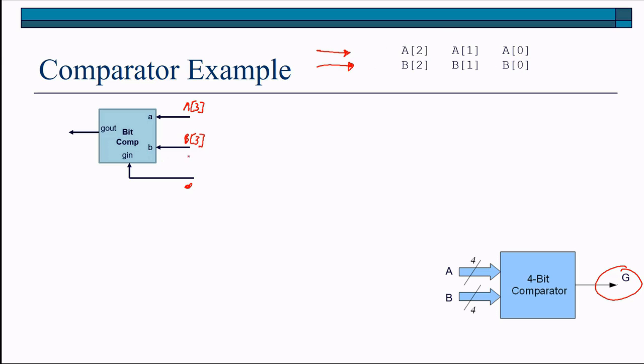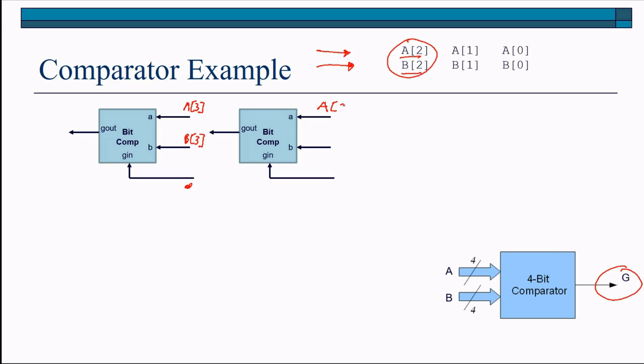And we can do that in a simple way by now considering 2 3-bit values and using the most significant bits from those 3-bit values to drive another single bit comparator. So for this second single bit comparator, we'll supply A2 and B2. And the input here for GN comes from comparing these 2 bits with these 2 bits.